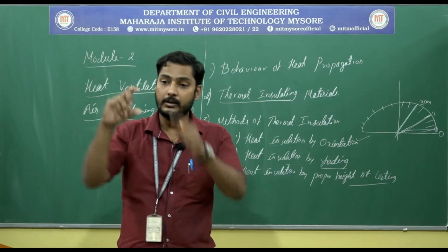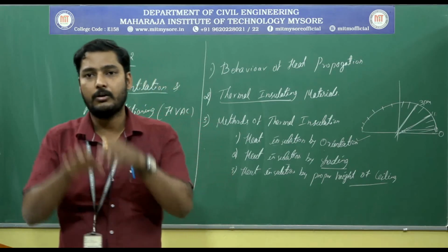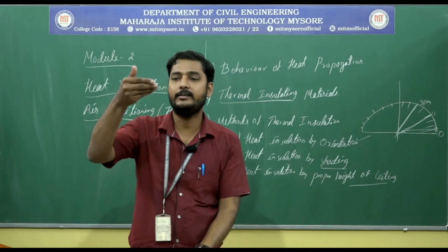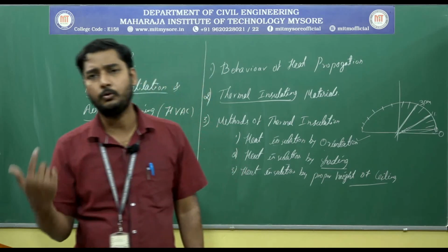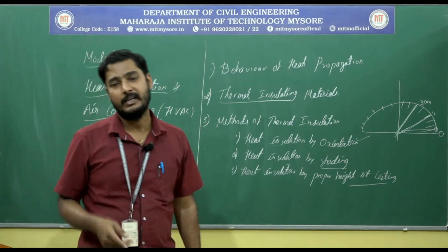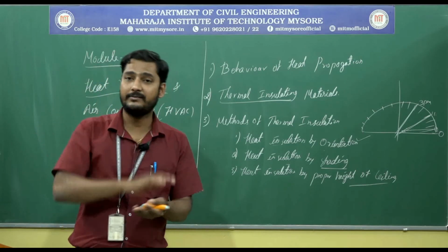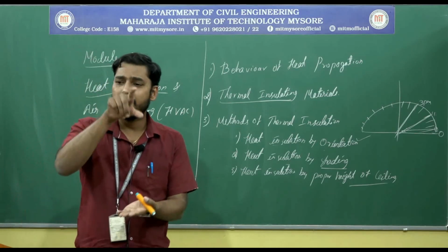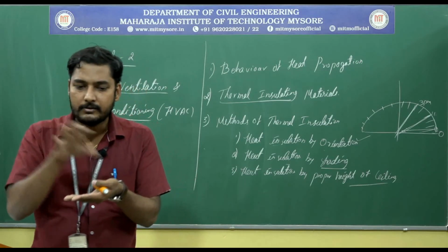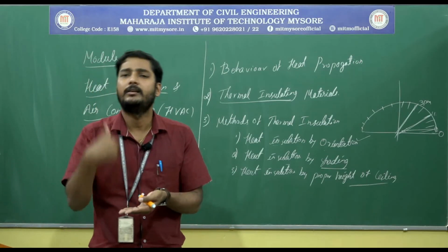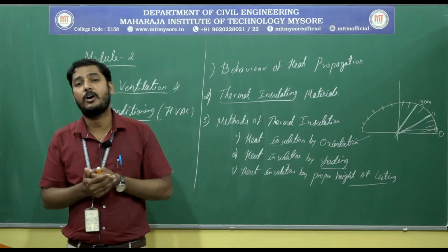the building height is said to be 3 meter. Yes or no? Because if we go below, 1 to 3 meter height of the building, automatically the heat liberated in that entire room seems to be a little bit high in nature. That's why we need to prefer 3 meter or minimum 10 feet as floor to ceiling height. In some cases we have minimized the height of the ceiling, so we can experience the heat transferring within that location because of the radiation. Because of the minimum height, the radiation process seems to be a little bit more in that building. That's why we experience that the room is a little bit hot in nature.